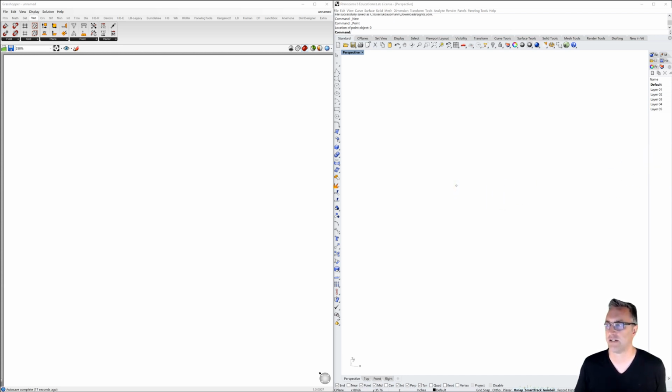So what I'd like to do is start with, as I said, let's start with just one line. And so I'll start at the origin. I'm going to make my first line 12 inches long, and I'll just constrain it maybe in the X direction. It doesn't matter which direction I do it, but I've just got this simple line. And the direction does matter. And so I started at the origin and I drew it to the right, and we'll be able to use that directionality as we go forward.